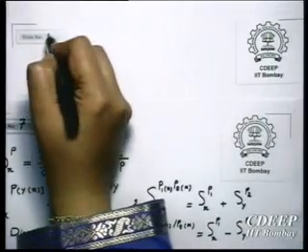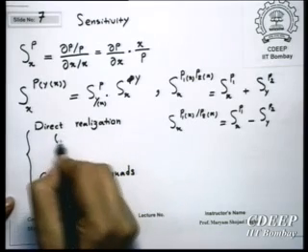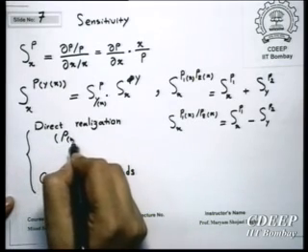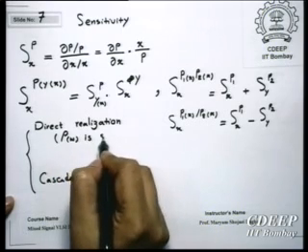It's not very straightforward. There are a few things. First of all, in direct realization, if we want to get a good sensitivity, we should make sure that rho as a function of omega is very small, at least in the passband.